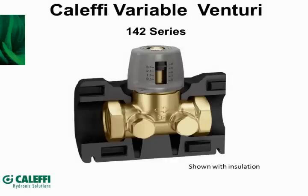Okay, so we looked at the balancing process for a fixed Venturi balancing valve. Let's look at a variable Venturi balancing valve, and here's a shot of Caleffi's variable Venturi balancing valve. Now, we'll use ours as an example, but it's a similar procedure as any other balancing valve out there in the marketplace. These balancing valves, by the way, are not available yet in North America. They will be sometime mid-year. These caps right here are where the pressure ports would otherwise be installed. In fact, when we come out with the balancing valve, we'll have the PT ports pre-installed for the market.